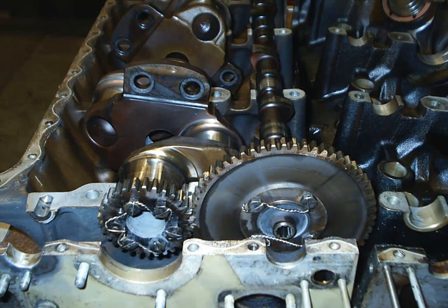Here's a picture of the inside of an engine, and you can see both shafts. You can see the crankshaft on the left and the camshaft on the right, and notice they're geared together right down here at the end. So once again, the valves are opening and shutting at exactly the right time in the four-stroke cycle. And because the valves only have to open half of the revolution, so every other revolution, the gear on the crankshaft is smaller. The gear on the camshaft is bigger, exactly double the size, so the crankshaft has to turn twice for every one time the camshaft turns.